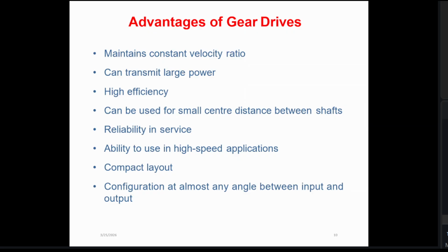Those centrifugal forces will reduce the grip between belt and pulley, and also increase the tension in the belt, right? Because the centrifugal force acts towards the circumference.